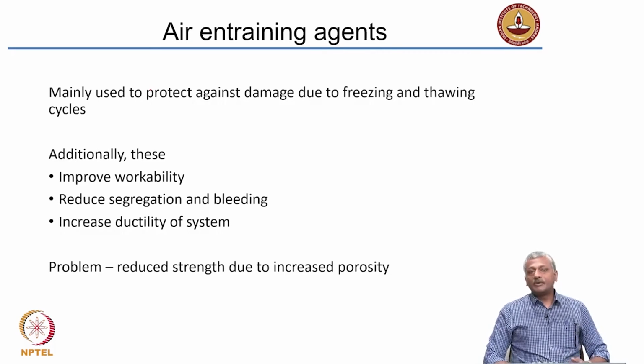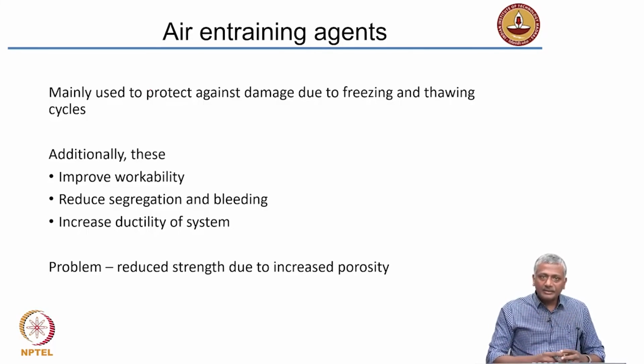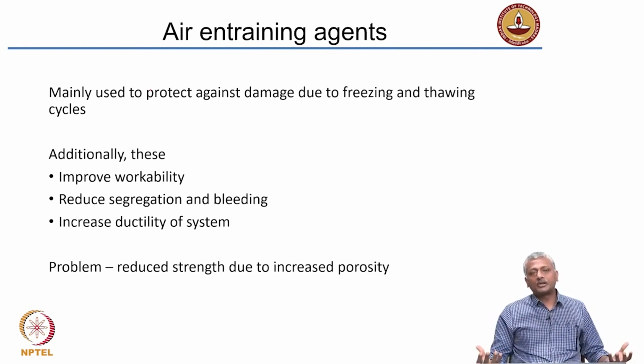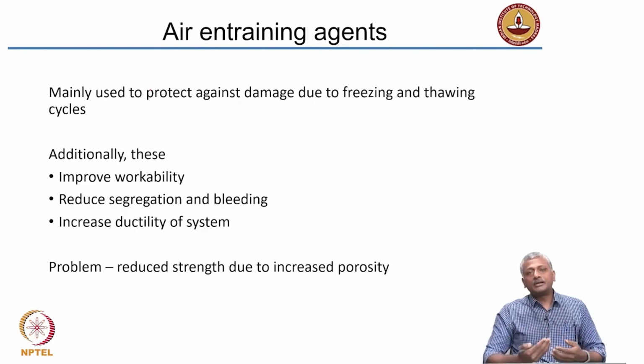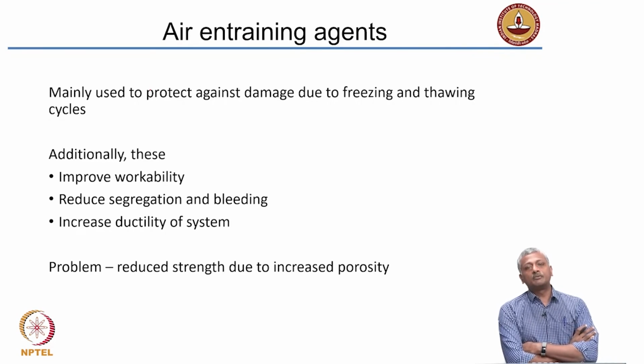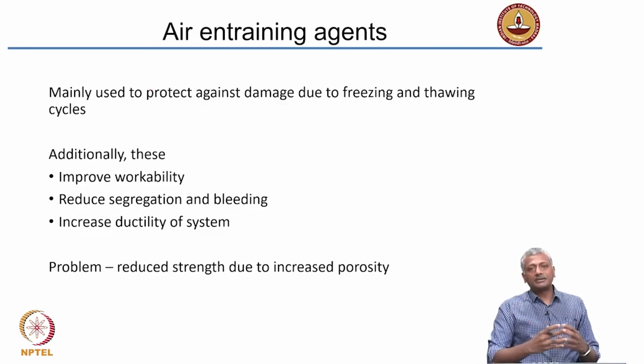Sometimes in very cold areas, you may get temperature fluctuations that can cause the water inside the concrete to freeze, and then subsequent increase in temperature causes it to thaw. So, it freezes to ice and then it changes back to water. Interestingly, for water, when it transforms to ice, it leads to an expansion in volume. Very few materials exhibit this behavior, right? You have an anomalous behavior with water. When you freeze it, it expands. And this expansion leads to stresses in the concrete causing cracking.